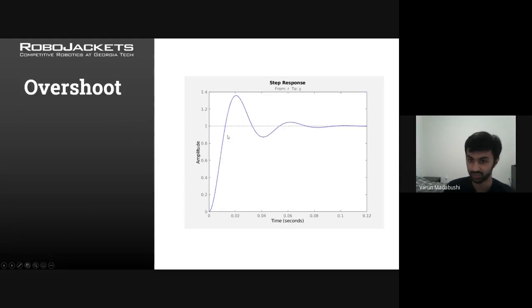And this is overshoot. Here, the robot will pass over the goal and then have to adjust back and forth. Overshooting leads to some oscillation. Over time, it may settle down, but it'll bounce back and forth. This happens when your gain is too high, like your proportional gain or your integral gain might be too much. Those gains are the constants Kp and Ki. If those are too much, you might end up overshooting because you're adding too much energy into the system.